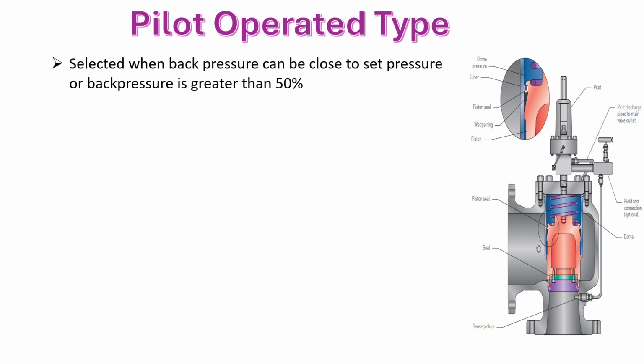We'll discuss the diaphragm type, which is typically only available for low pressure applications, and it produces the proportional type action characteristics of relief valves used in liquid systems, and therefore there is little use of such safety valves in steam applications, and they will not be considered in this steam application case.